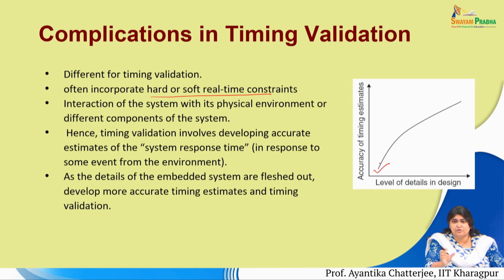It may happen that for the block we are considering, we are just looking at the initial level, the execution time for the code specified for that block. But we are not considering the communication delay if that block is waiting for some input coming from other blocks, and that will be governed by the overall communication delay present in the system. So, if we just focus at the granular, lower level, our accuracy may not be so correct,